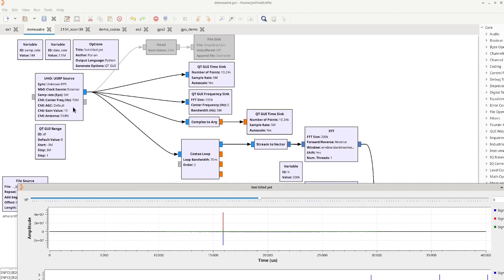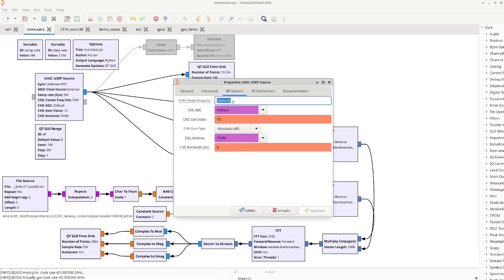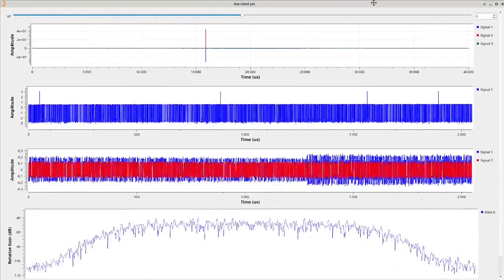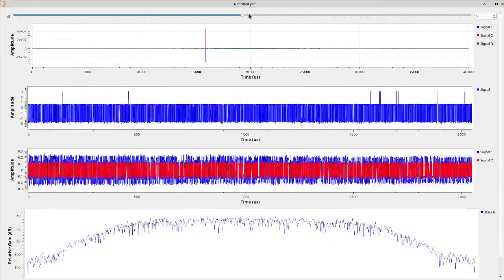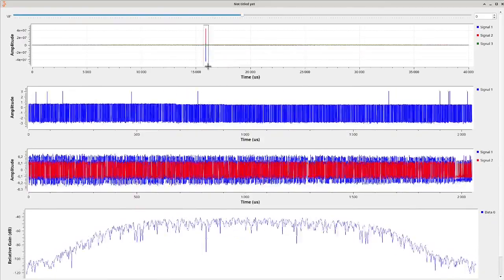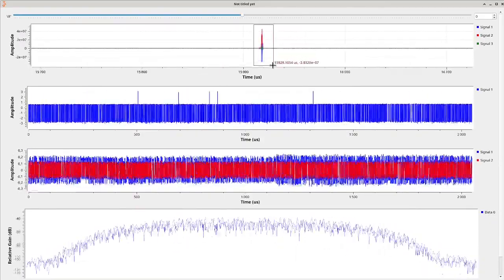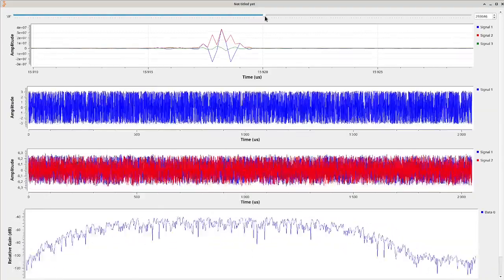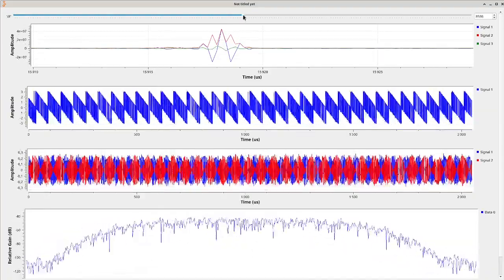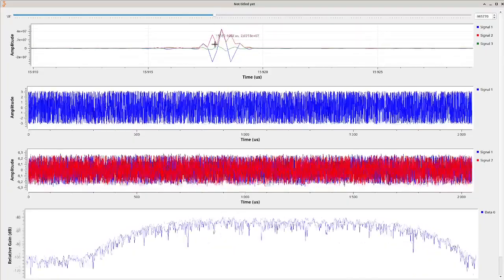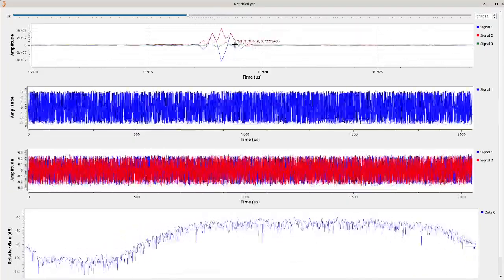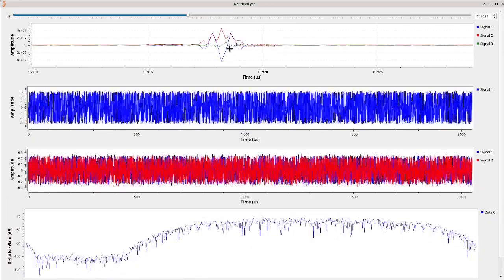Here we are introducing on the carrier frequency an offset df, and this offset df is the one we can tune over here. What we do see is that the correlation peak is static since both ends are clocked by the same frequency source, but even adding a frequency offset does not impact the code delay that represents the frequency difference between emitter and receiver.